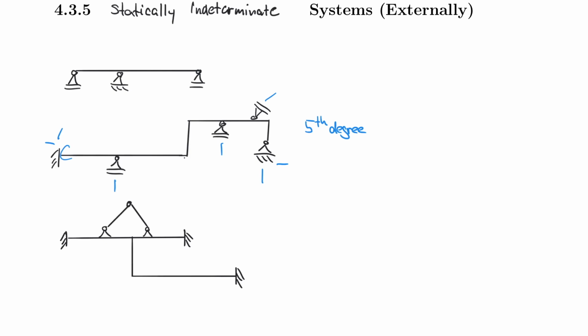And so now be careful, right? Because here you actually have a statically determinate system on top of a statically indeterminate system. So what I'm trying to tell you here is that this is your hinged, simply supported frame that is statically determinate, and it just sits on top of the structure. So this is just adding forces to the system. So this is not counted in my statical indeterminacy, but I have 1, 2, 3, 1, 2, 3, 6, 1, 2, 3, 9. And so this is to the 6th degree, right?